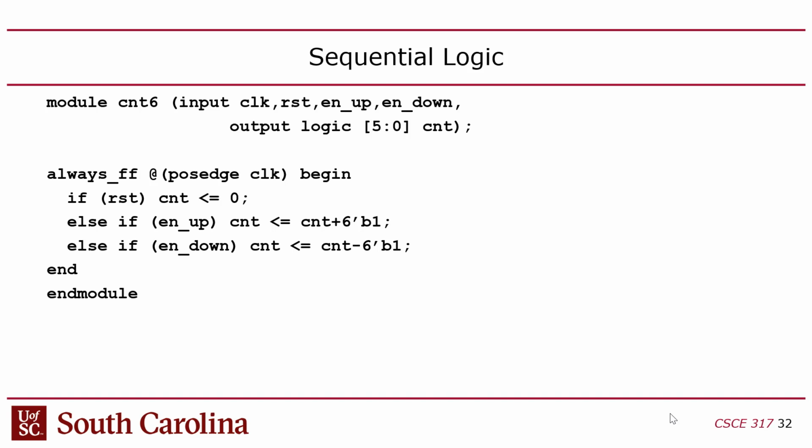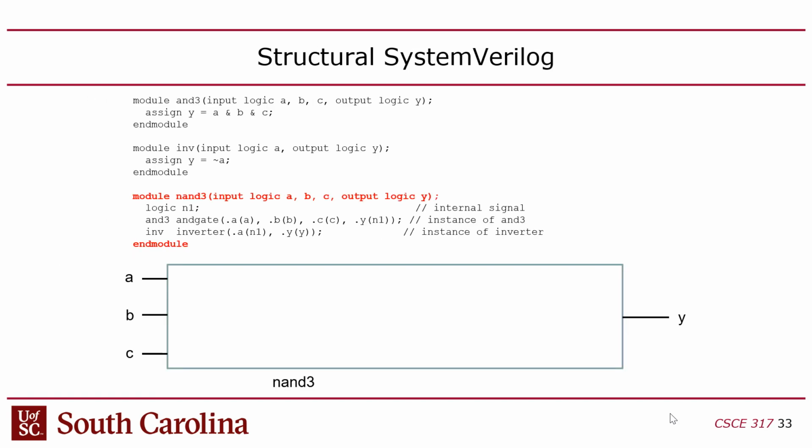The problem is that when you do that, Platform Designer forces you to use Verilog and not SystemVerilog. So that underscore FF won't work, because for whatever reason, when you do a module for Platform Designer, they don't let you use these SystemVerilog features. So that's why I'm pointing this out. Okay, and I'll talk more about that a little later.